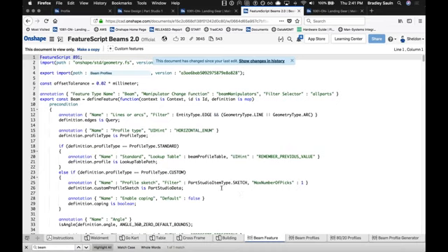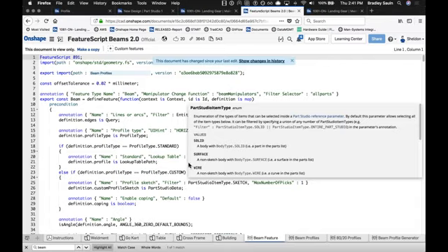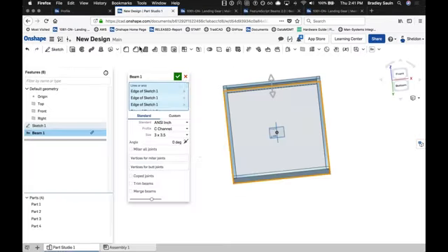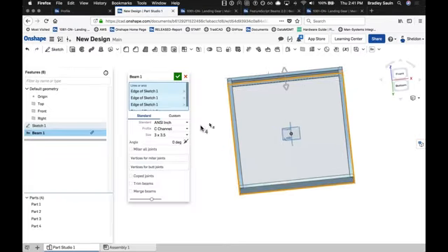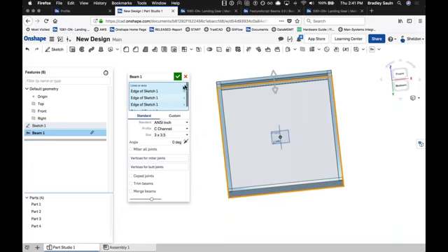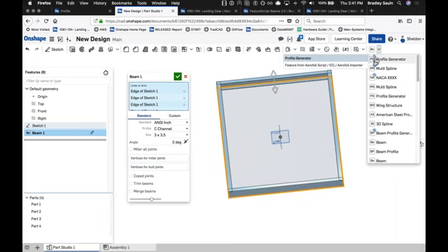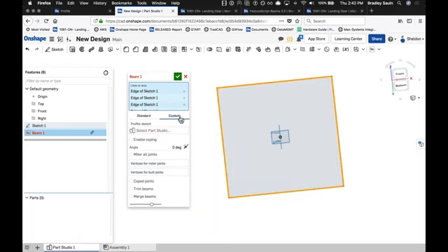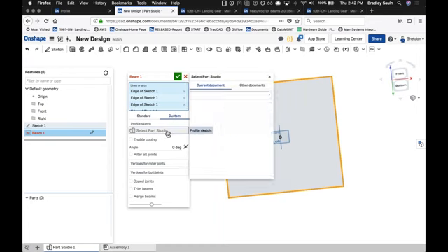But we've now introduced this new capability in FeatureScript to be able to reference certain parameters. So if I go back to my new design, and if you have the beams feature, actually you should update this. You'll notice a little blue link icon, just like a linked document, where you can right click and choose to update this, because we've added a new option here to actually create a custom beam profile. With this reference parameter, this acts just like the derive tool, essentially.